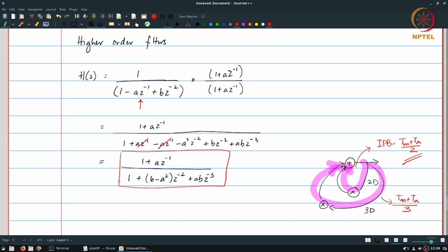This is not restricted only to IIR filters. One of the places where it has found significant use is the Viterbi algorithm, where it turns out that there is a similar kind of loop. There is a loop in the structure where you need to add a certain metric value, compare it against the previous metric, and then decide which one is the survivor. Once again, it looks very similar to an IIR type of filter.